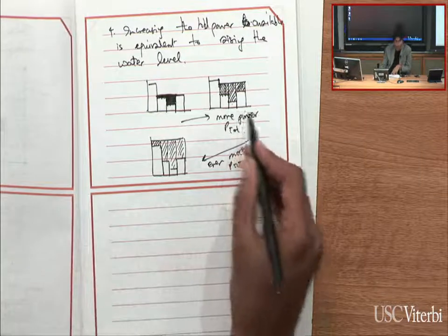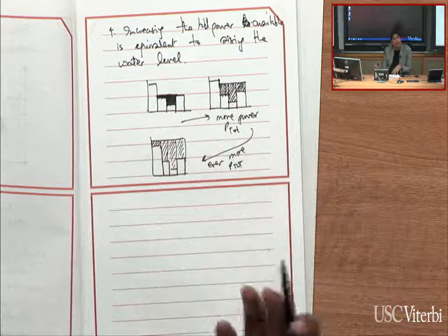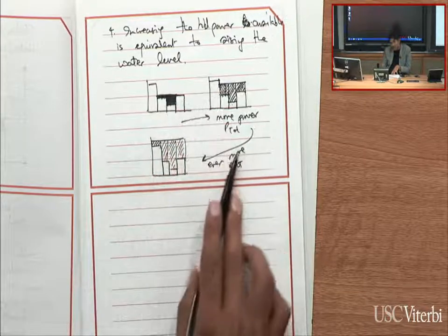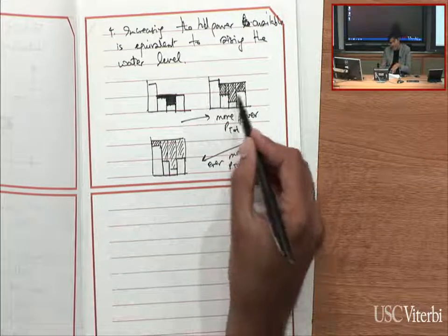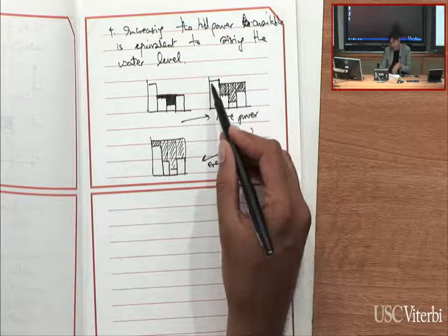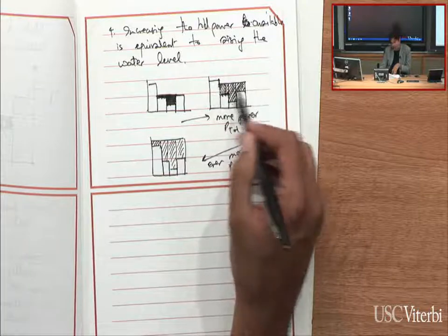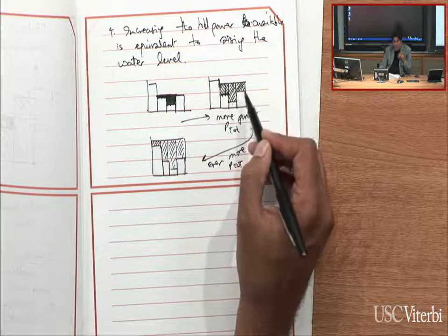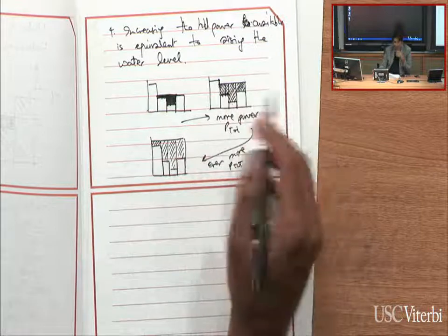And as you allocate more and more power to each channel, its rate is getting better. We know that from the original Shannon's equation. The more power you can put in, that log of 1 plus SNR is going to go up because SNR went up, and so you're going to get more rate. And so certainly as you have more power to spare, you're increasing the overall rate. But when you have a certain amount of power to spare, this is telling you the amount you should spare to each channel. The way you do it is you kind of plot the noise to gain ratios, and then you fill up to a certain water level, right? And you choose the water level in such a way that the total sum of all of these heights adds up to your available total power. So that's sort of the water filling solution.